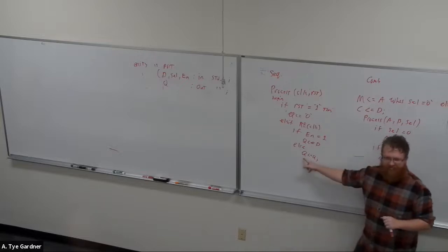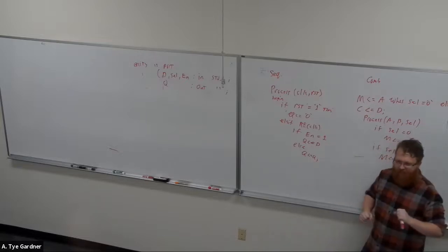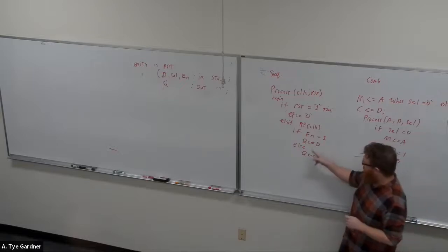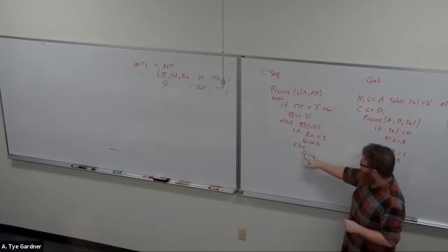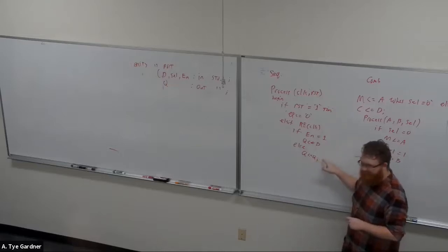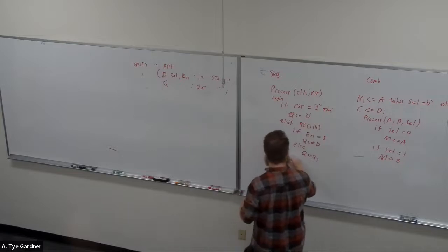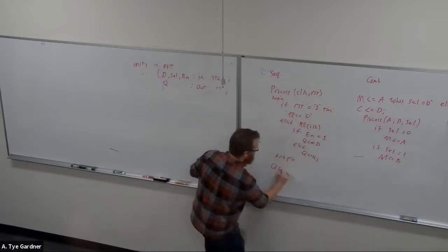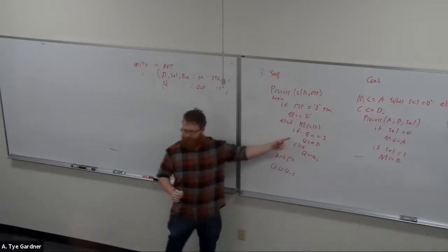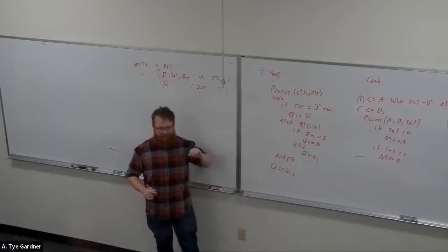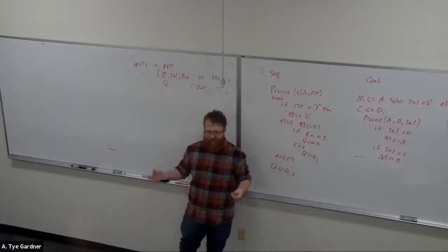What is the right way to fix this? Yes, create an intermediate signal called like Q underscore S or something, and then we can assign QS to QS. That works. And then outside of the process, I can just say combinationally, Q gets assigned to QS, where this gets replaced with QS. That makes it so that we don't have an output on the right side, which is never allowed.